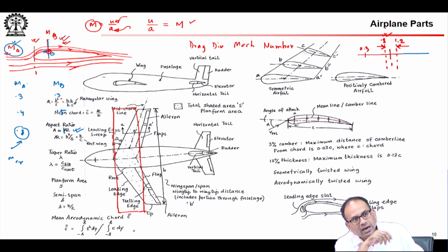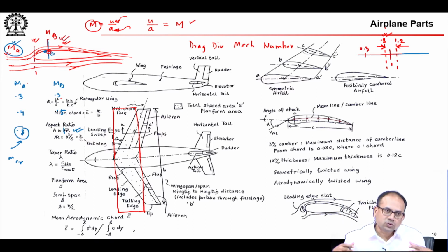That is, at Mach numbers around say 0.8, as the flow goes over a vehicle geometry, say the fuselage or the wing, primarily the wing, on the top surface the velocity increases and it can reach sonic speed. So, Mach critical is that Mach number where flow becomes sonic for the first time, and it somehow defines the start of that transonic window. So, that is critical Mach number.